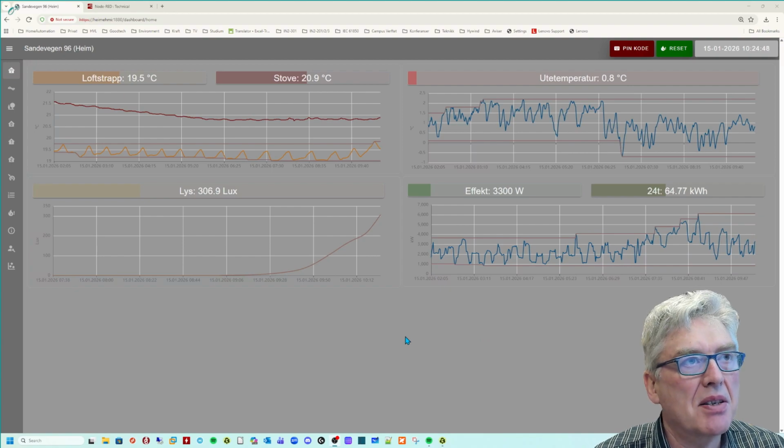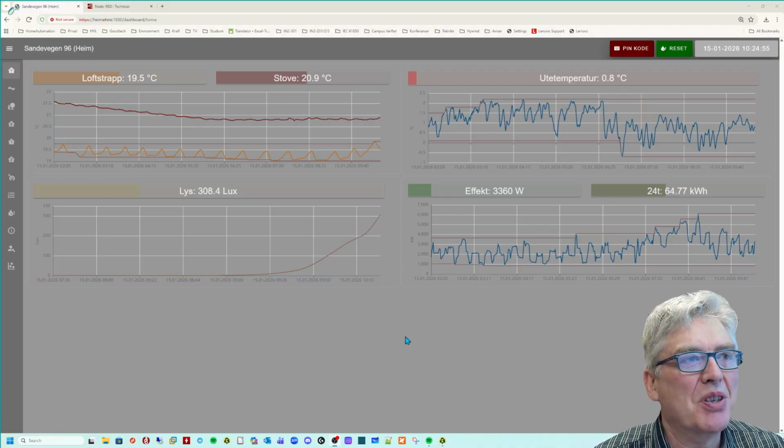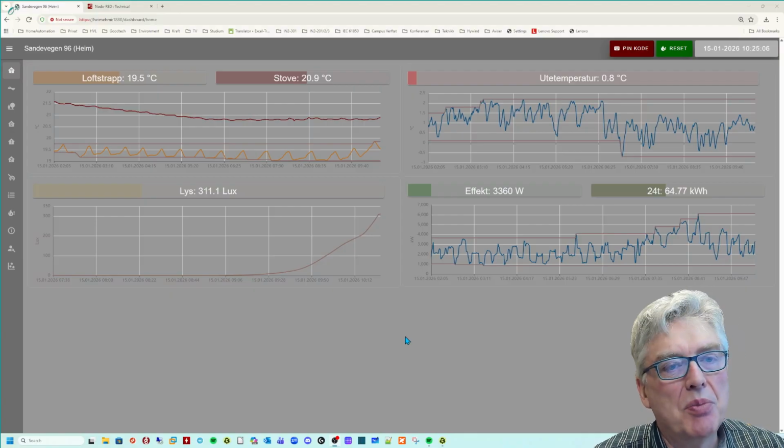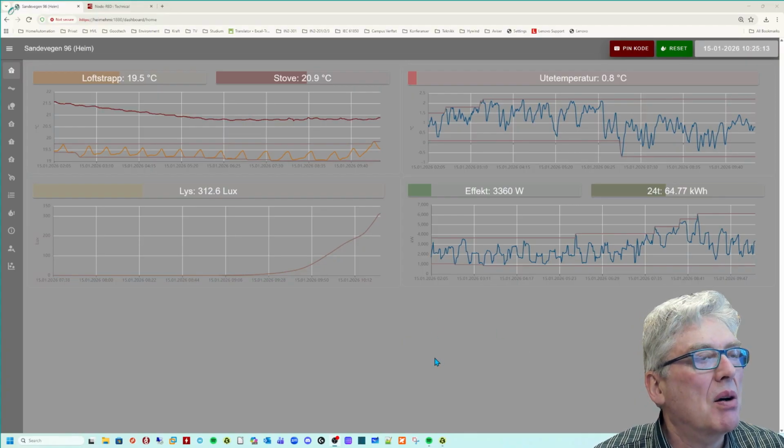I have a Simatic S7. It's an old one. It's been running for 20 years and it's running fine. I probably have to upgrade it at some point in time now. Of course, in Node-RED, you have a Simatic S7 driver. You even have OPC UA, but as my CPU is old, I don't have OPC on it.